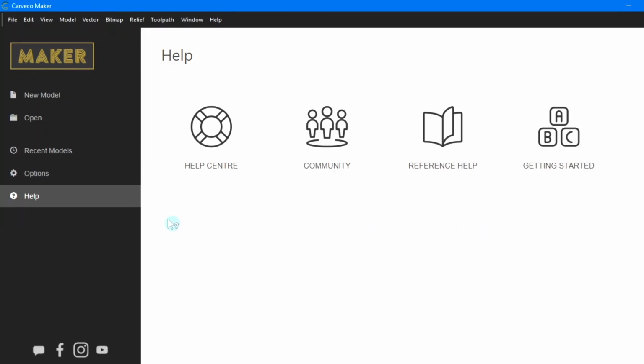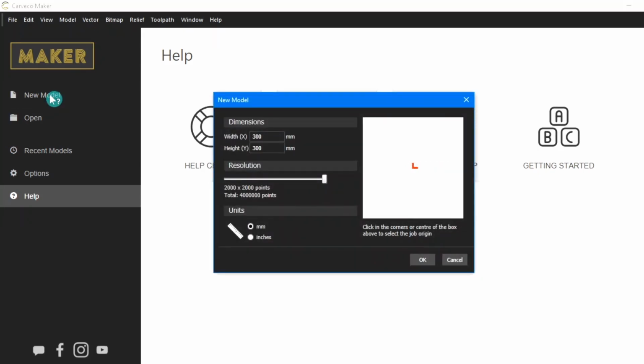That obviously you can look through, but I would suggest not to alter anything else in that dialog box. So the next thing we're going to do is to prepare to open a new model or a new piece of work. So we open this up. Now I normally work in millimeters, but obviously if you wish you can work in inches, so you can just toggle back and forth here to suit whatever you want to use. So I'm just going to alter this a little bit. In X I think we're going to go 400 to make it a rectangle piece of work.